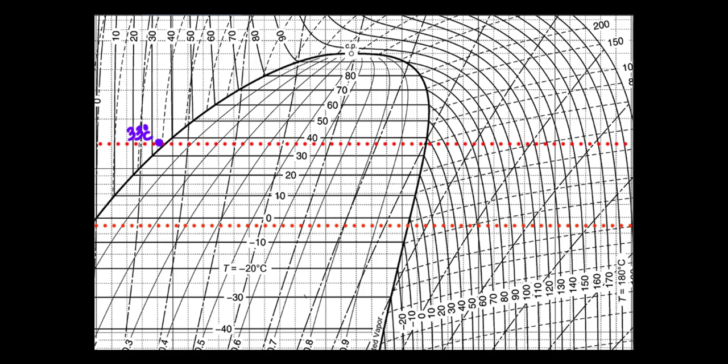So we superheat by 5 degrees Celsius. Referring here, we have 0 and 10, so it'll be in between. We can assume it's around here. Plotting that, we have the intersection of negative 2 to 5 degrees Celsius superheating. I'm going to write here our 5 degrees Celsius for superheating, and this one is our negative 2 degrees Celsius. Now we have our point 1 prime, and at this point, this is our point 1.